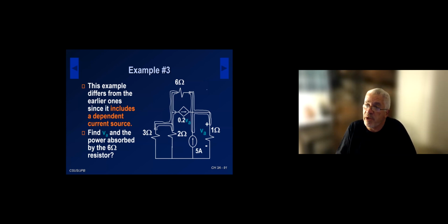So you see, generally the nodes are not going to be nice dots. You're going to have to identify them correctly because the node voltages are the voltages at these nodes. If I don't have the nodes correctly, obviously my entire solution fails. And finally, at the bottom here, I can start right here at any element at the bottom. Wherever I'm on a wire, I am in one node, until I touch an element.